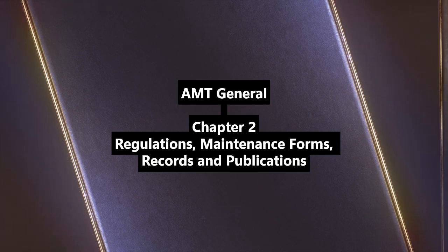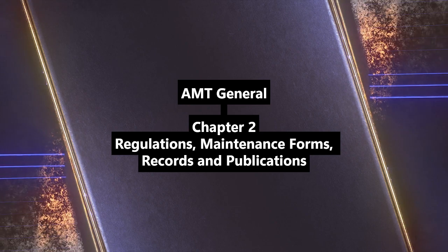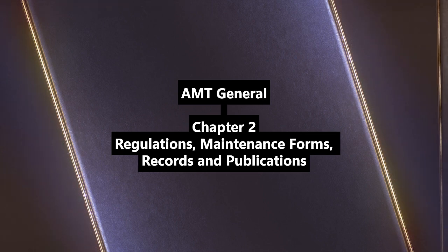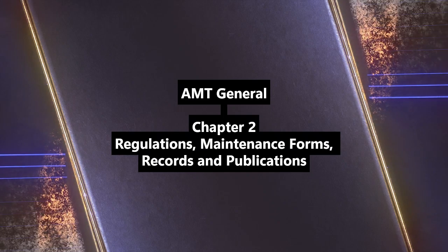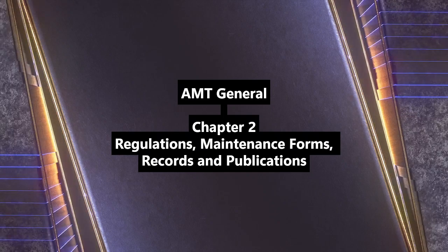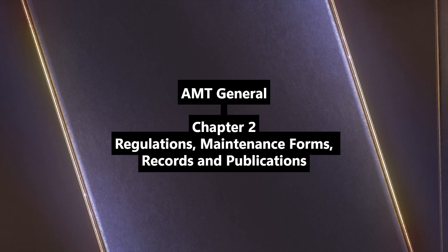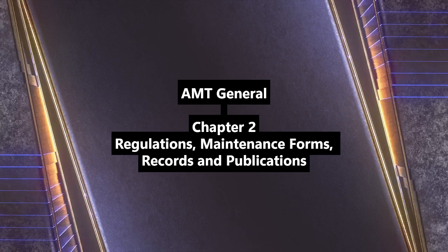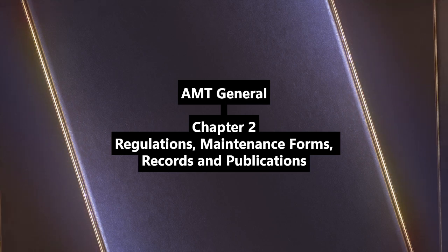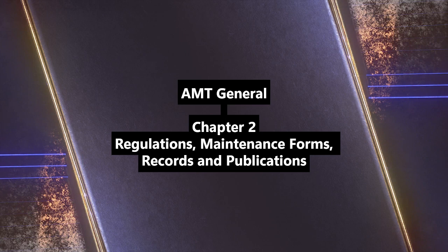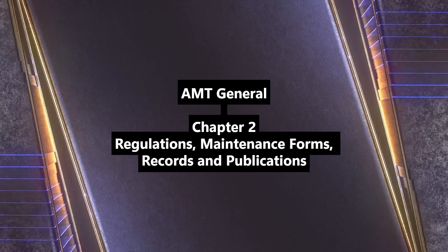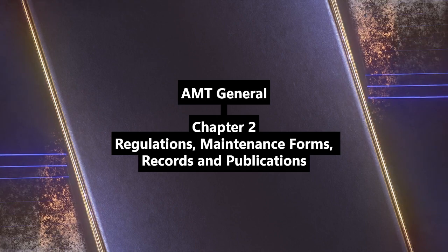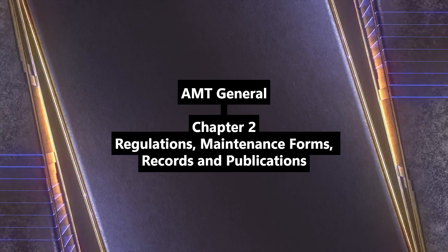That brings us to the airworthiness standards, starting with 14 CFR Part 23. This covers normal, utility, acrobatic, and commuter category airplanes. So most of general aviation, trainers up to small turboprops. Generally, yes. The limits are usually 9 or fewer seats, though commuters can go up to 19 and a max takeoff weight of 12,500 pounds, or 19,000 for commuters. And it details the design requirements. Yep. 7 subparts covering flight characteristics, structure, design and construction, power plant, equipment, even the flight deck layout.